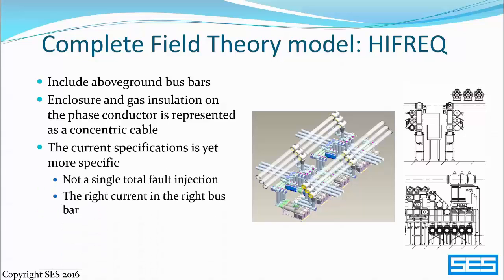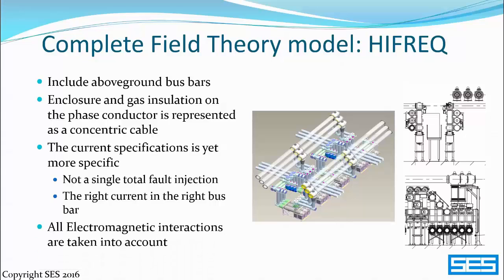The fault current is also more specifically specified in this model since now we will be tracking the effect of current flowing in the bus bars. Each fault contribution is listed independently rather than the total fault current. The whole purpose of this model is that finally all electromagnetic interactions are present. Specifically, the addition of induction in this scenario is going to have a substantial impact. Let's load the HIFREQ model in SESCAD.